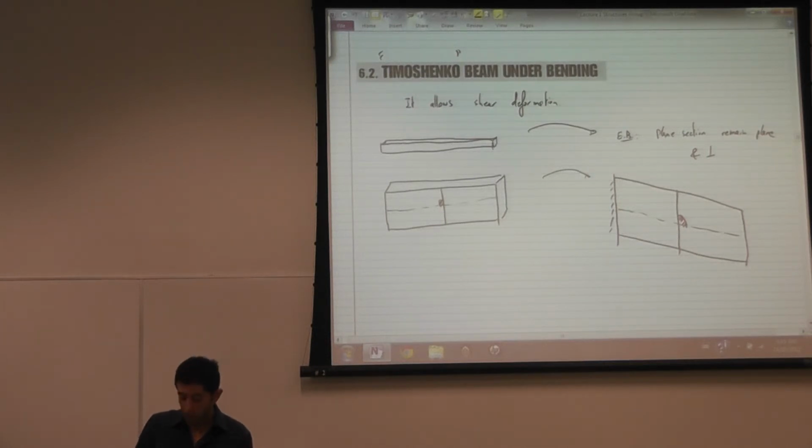They're applicable for deeper beams, but if your beam is that deep, finite element analysis would be better, simply because finite element analysis would not put that restrictive assumption of plane sections remain plane. In a finite element analysis, maybe each element would have a plane, like the side stays plane, but the next one doesn't necessarily need to be on the same plane after deformation.